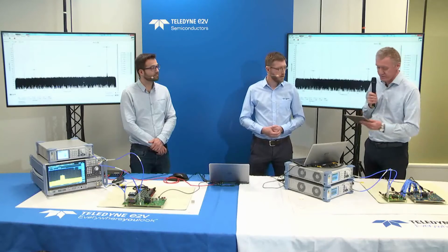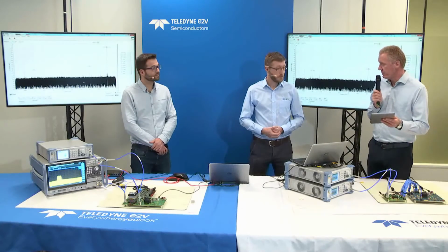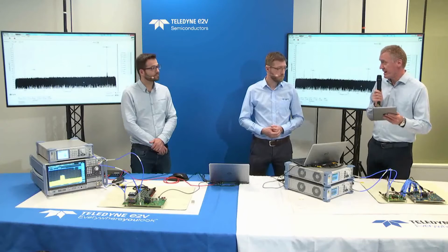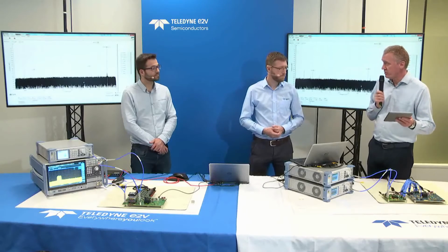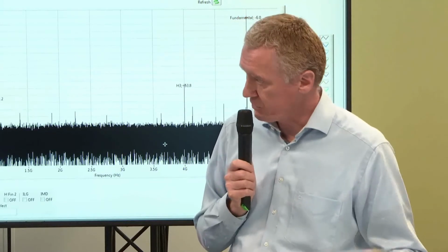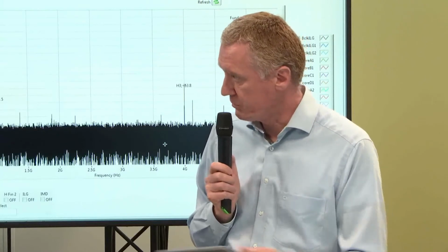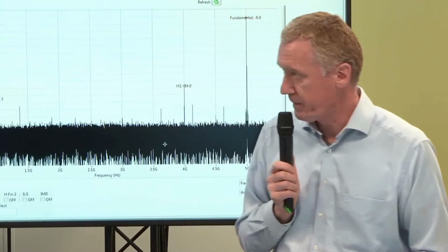Maybe we didn't really emphasize, but this is a single-ended input, so maybe that's going to help to distort less compared to what is done with today's gigahertz class ADCs. With previous generation of data converters, people are forced to go from single-ended to differential, which really is not helping on this question. Yes, the single-ended input can help. How can you comment on that, Romain?